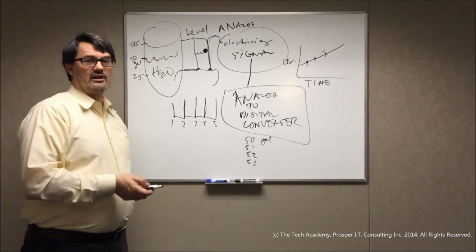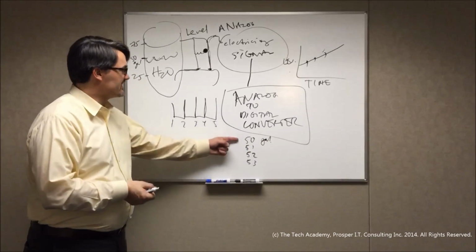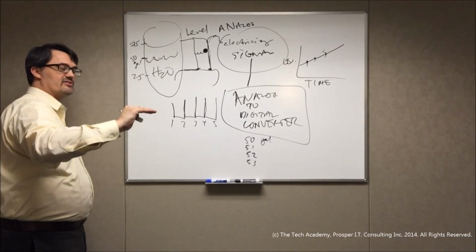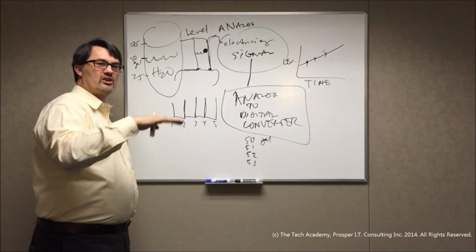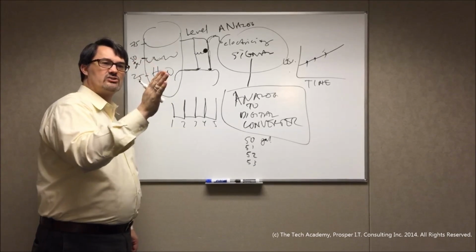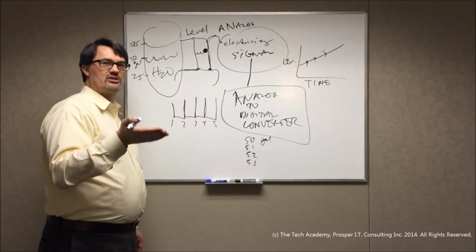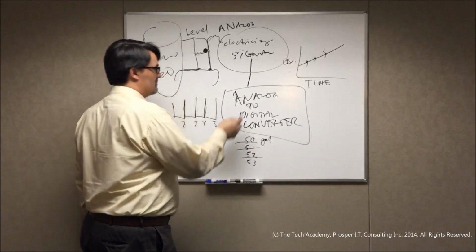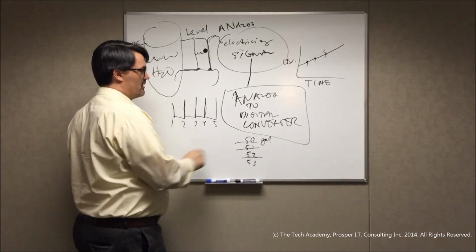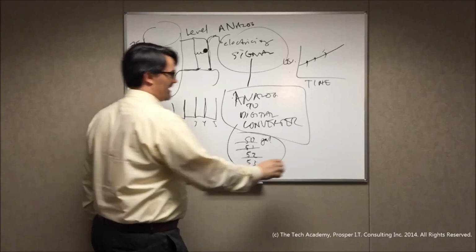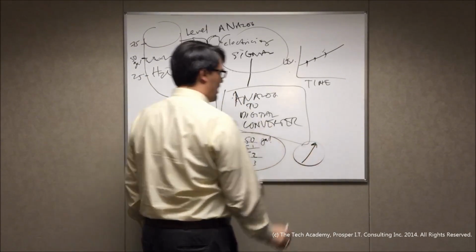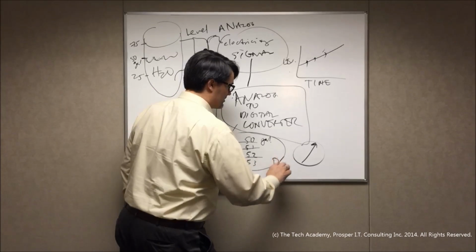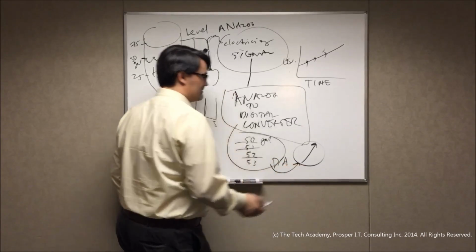This is not analog anymore. The signal coming out isn't exactly like what this is doing, because the water level is increasing at a rate over time that you can watch happen, and there's no set jumps, it just is continually changing. To convert it to digits requires an analog to digital converter. And then if you actually wanted to take this and display it on a meter, well, now you've got a problem. You would actually require a separate thing called a digital to analog converter to turn it right back.